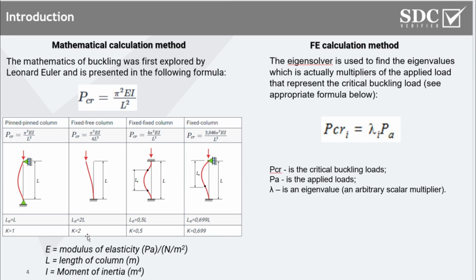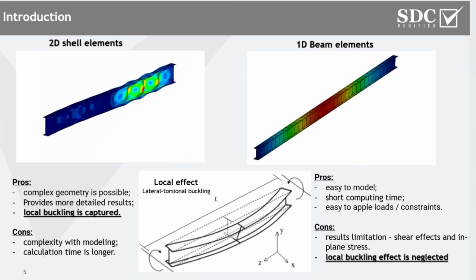So for this purpose I prepared this one slide, because most steel structures, lattice structures, can be executed with beam elements. This is the quickest and most convenient way to do this. And we don't need to play with the geometry and overspend our time to prepare a model. Besides that, it also speeds up the calculation process.